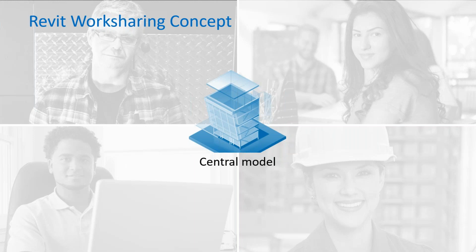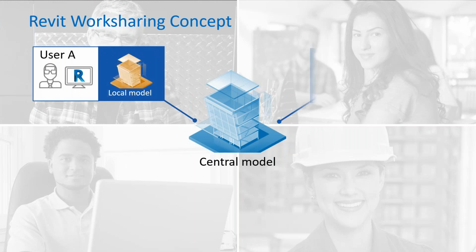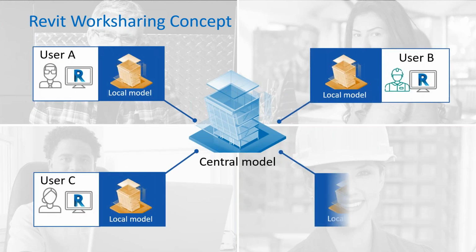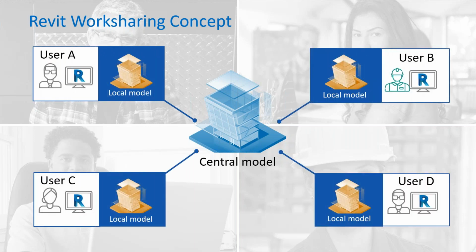And so I need to get across this concept of BIM 360 design. And actually, I keep saying the concept itself isn't new. What we've done is we've hooked up the cloud to this concept. So essentially the concept is work sharing, worksets, save to central, reload latest, relinquishing objects, claiming objects. Essentially you have a central model, you have different users with their local models, and they're going to communicate with this central file, if you will.